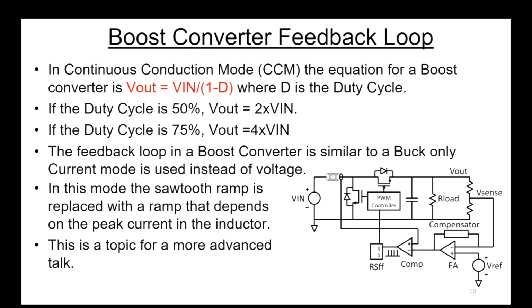And that means you're probably going to oscillate. Supposedly, by using this current mode feedback, companies have been able to address that. What they do is they sense the current coming out of the inductor, and instead of that sawtooth ramp that we fed into the comparator the last time, now we're feeding a ramp that's a representation of the current through the inductor. And then that is used through an RS flip-flop with the set periodically being pulsed with a clock.